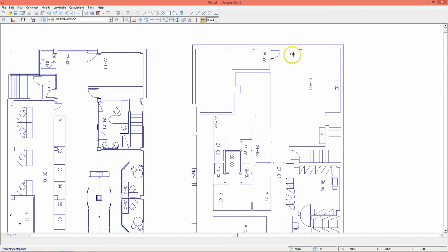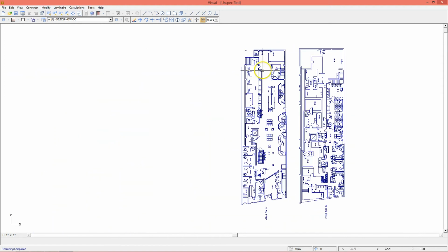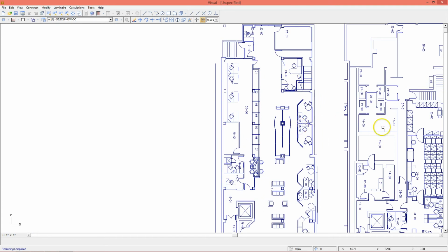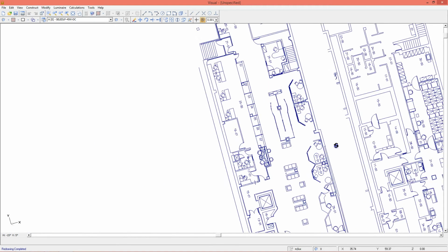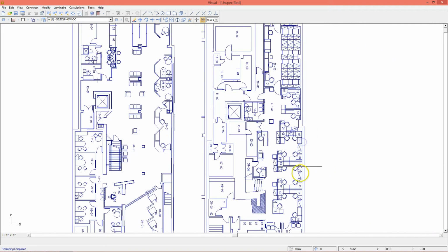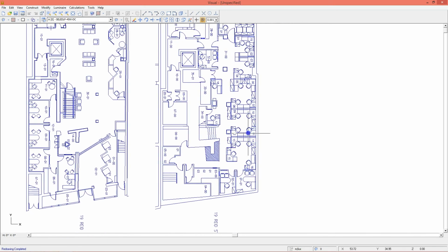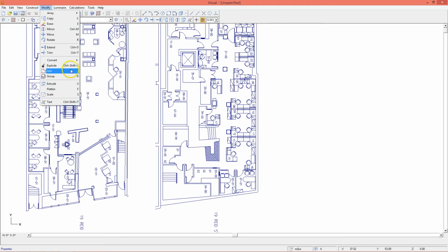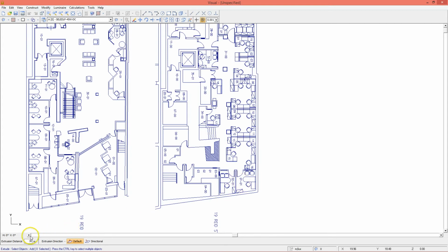So what we do, I'm just going to do a section to keep it simple. Let's choose a section. We'll do these rooms down here. Okay, so we can have a look. Initially I can go here, modify, and do an extrusion, so this is what I want to start with. The extrusion distance at the moment is set to 30 meters, so obviously we don't want that. We'll set that at, let's just say 2.7 meters, or let's just make that 3 meters.